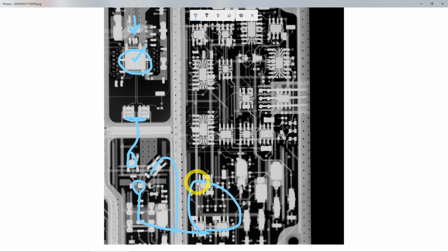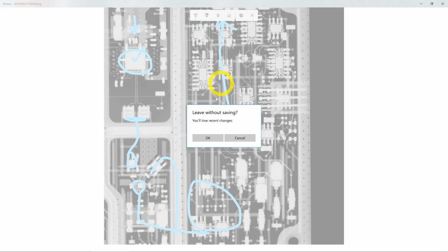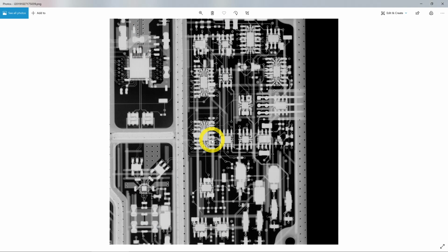So I was wrong when I thought that the entire PLL functions at lower frequencies were handled by the FPGA. They're not. They're actually done using traditional phase frequency detector, charge pump circuitry, and so on. There are D2A converters for the digital tune, but the analog part of the VCO loop is traditional, the way it's always done. So that's interesting to see. Above here is right where the VCO is, so you can clearly see the PLL loop wrapped around it. This is pretty complicated, but I'm going to try and see if playing around with the VCO components would help the operation here.